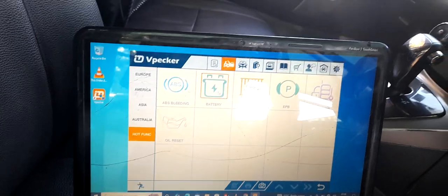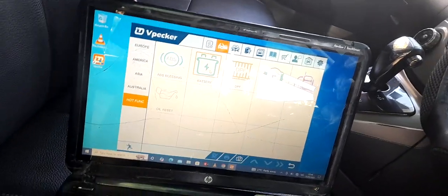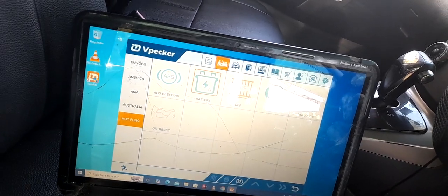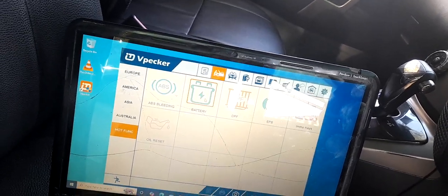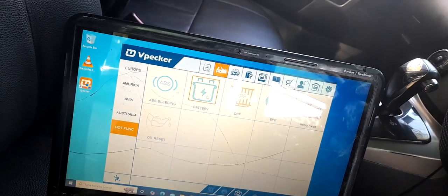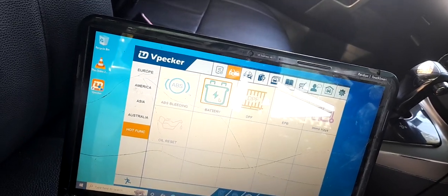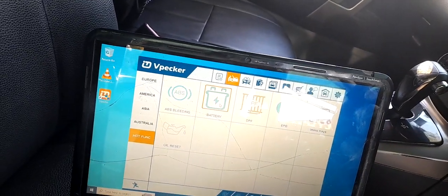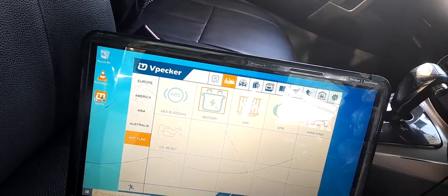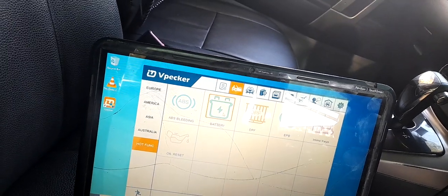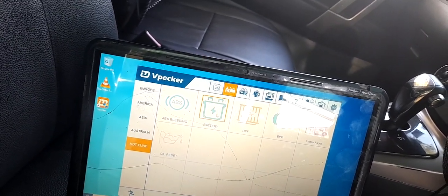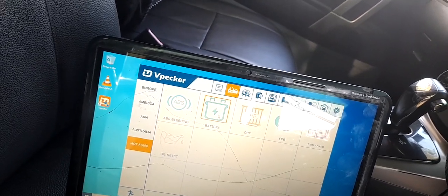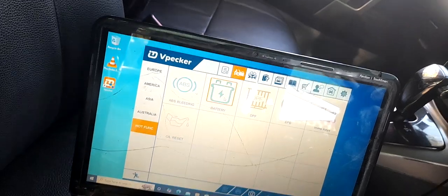And battery reset, now this one goes to BMWs. BMW has a feature for this. You cannot just change the battery like that. You need to alert the vehicle that you have changed the battery. Why? Because as the old battery's power becomes low, the vehicle's computer tells the alternator to increase power to charge the battery.